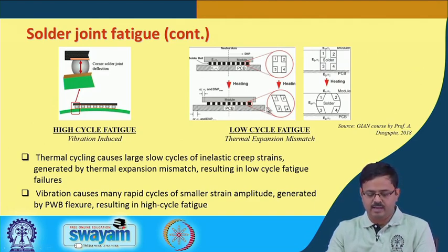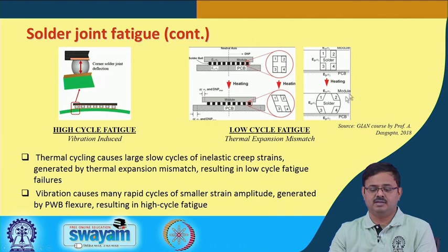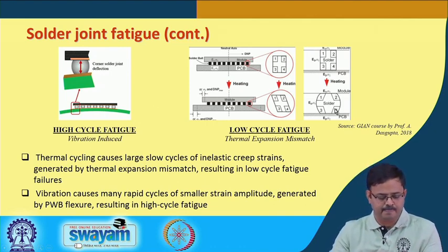This was the original condition, and this is what it is on heating. But in reality, even within the solder ball, if these are the four corners, the four corners are going to undergo stresses differently, correct. So, we need to understand these. This will see more strain, this will see more strain, these two, 2 and 3, not so much, 1 and 4 much more, right.